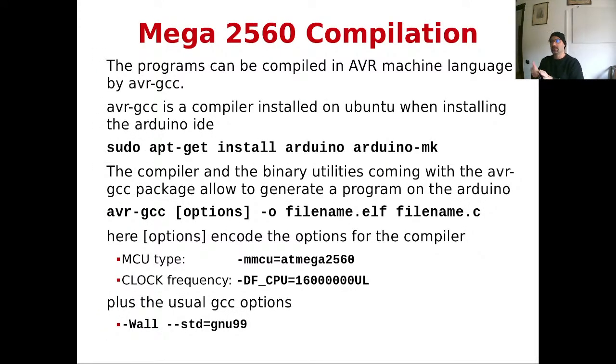To this extent, what do we need to program this microcontroller without an IDE? For sure, we need a compiler, and for sure we need a program that talks with the bootloader on top of the Arduino in order to write our program, right? Now, the good news is that the compiler for that specific architecture comes together with the Arduino package, and so does the program for uploading the data onto the Arduino.